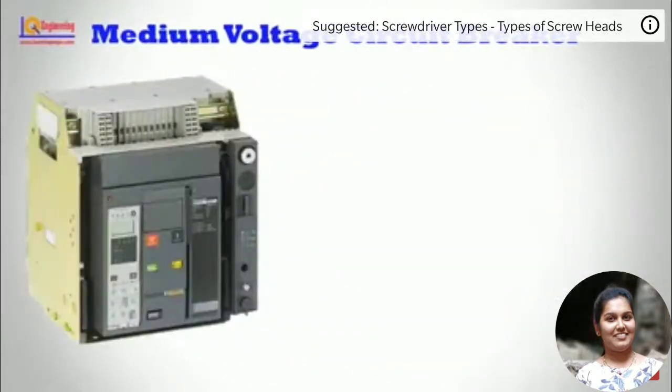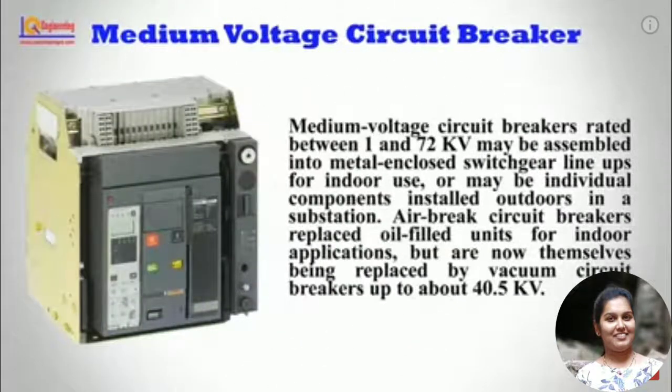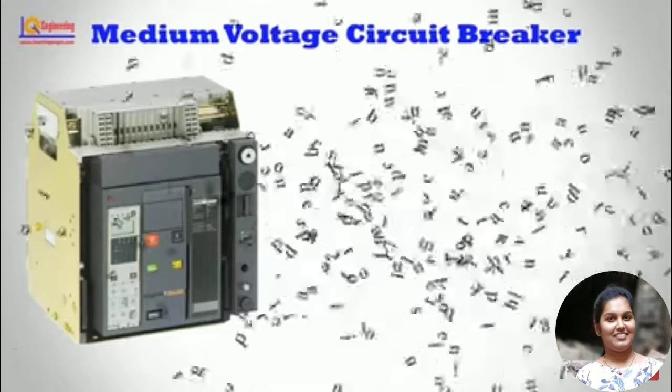Medium voltage circuit breaker. Medium voltage circuit breakers rated between 1 and 72 kV may be assembled into metal enclosed switchgear line-ups for indoor use, or may be individual components installed outdoors in a substation. Air break circuit breakers replaced oil-filled units for indoor applications, but are now themselves being replaced by vacuum circuit breakers up to about 40.5 kV.